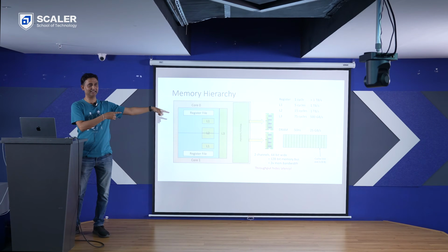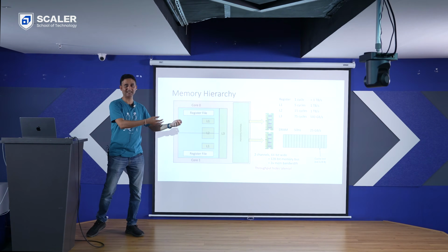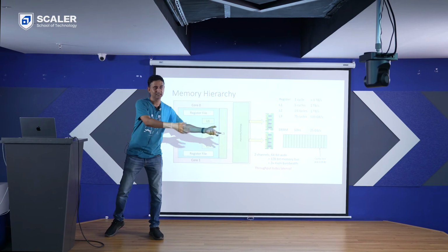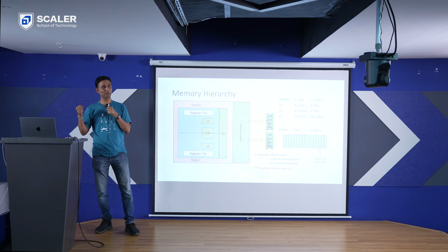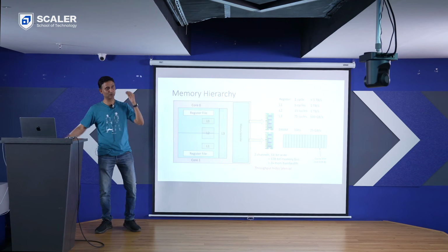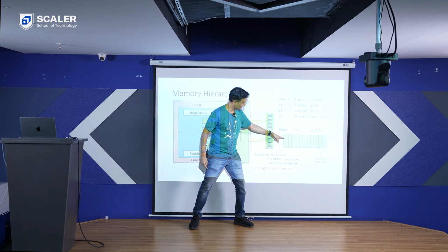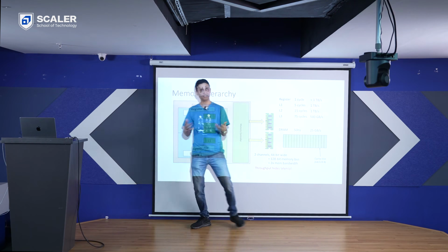So do you see how this is linking up with the cache line? Burst length correlates very strongly to the cache line. When we make a request, we actually get more than what we asked for, and that whole thing is pumped into a cache line. Say for example we ask for this data, the rest of the data we get for free, which is why nearby accesses become super fast.